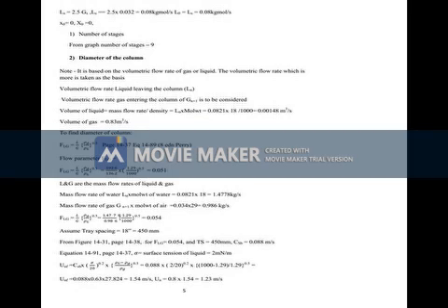That is 0.00128. That is capital Y1. Then you find out small y1. All these things, now you are very thorough with it. Then find out Gs. What is Gs? Gs is the molar flow rate of pure air. If you subtract acetone, what is the data?